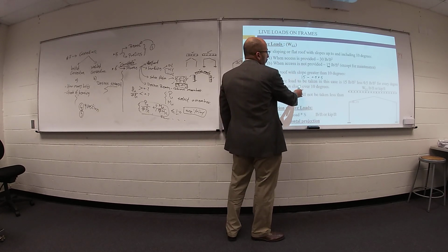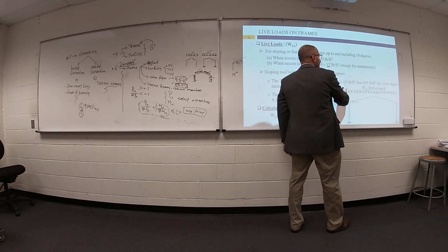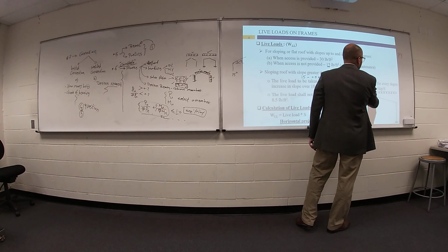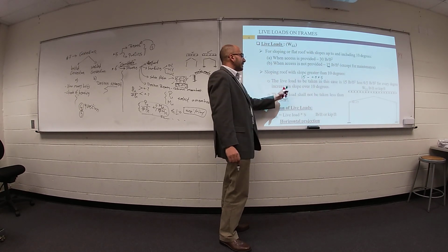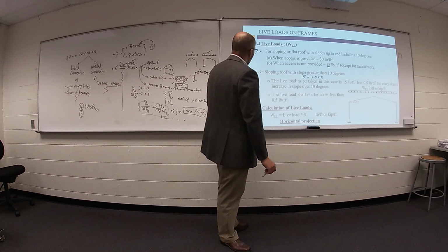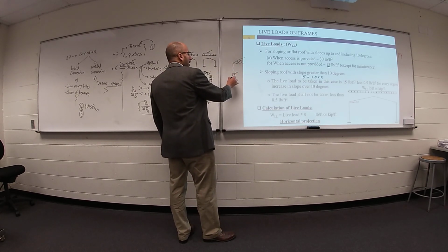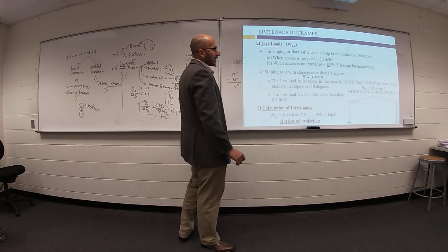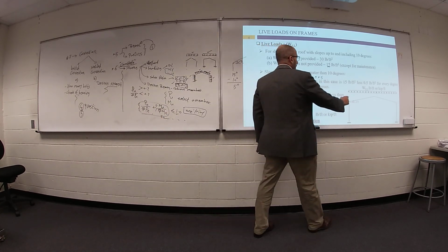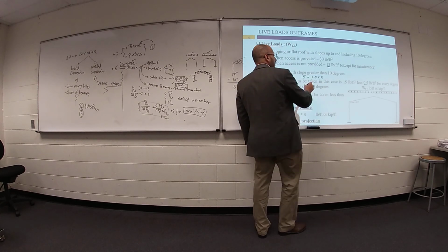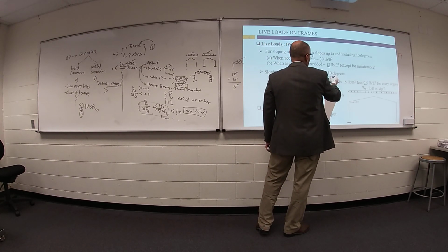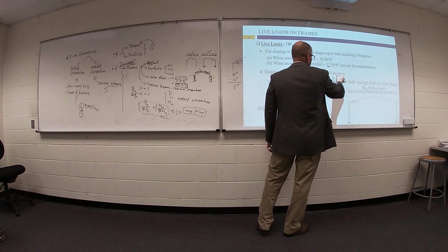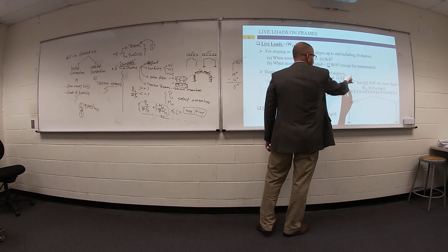So the live load to be taken in this case is 15 less 0.5 for every degree increase in slope over 10 degree. So your degree is 15 minus the original angle 10, you have extra 5 degree. Multiply this value by 0.5 and subtract it from the 15. Your value will be 12.5 pound per square feet.